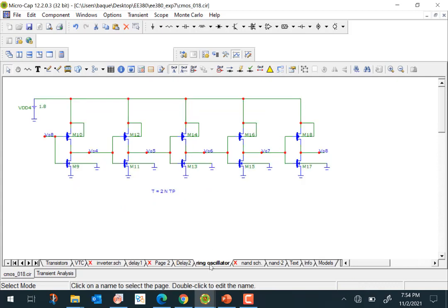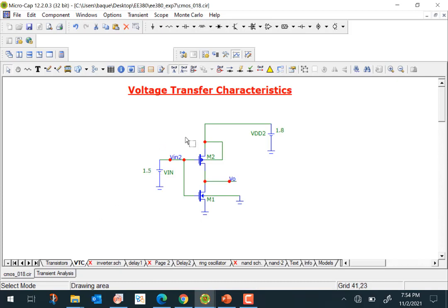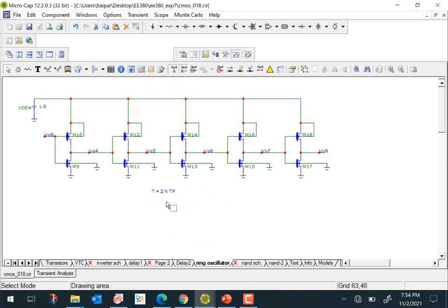Okay, so that's the part about the inverter. So with this, after doing a characterization of this particular part, the measurement of delay and power dissipation, and before that the measurement of noise margins and inverter threshold voltage, and then making a ring oscillator and measuring the average propagation delay, these are the means by which one characterizes a CMOS inverter.